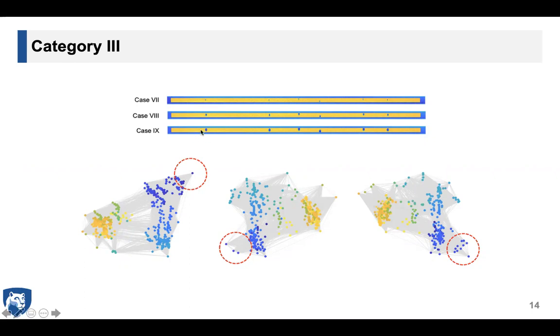The nodes shown in those red circles are associated with the porosity defect. As the size of porosity goes up, they become more noticeable, and the number of nodes in the cluster also increases as the size of the pore increases.